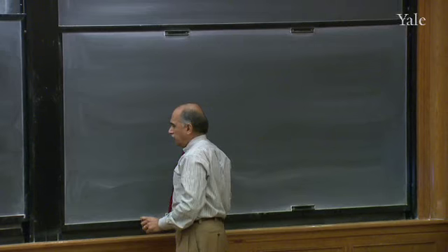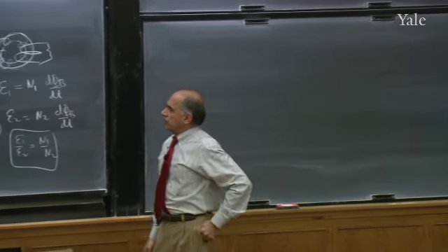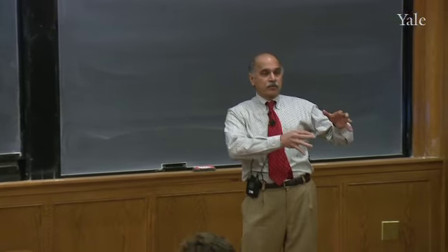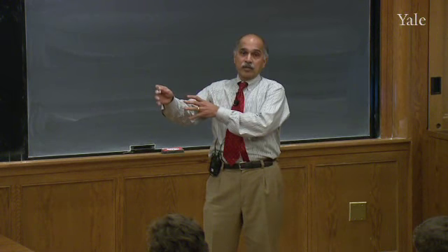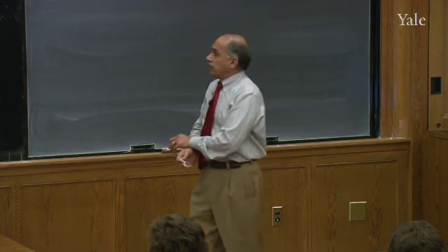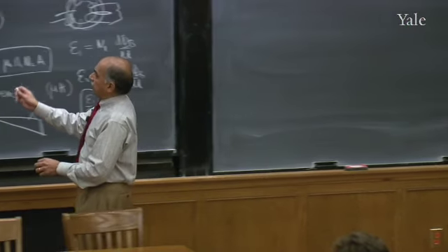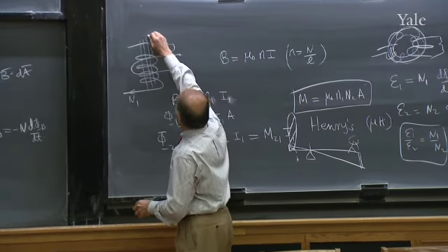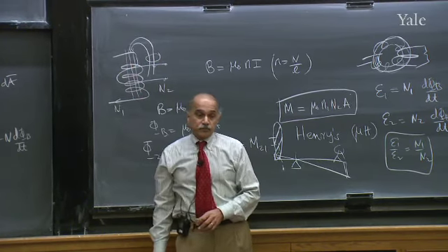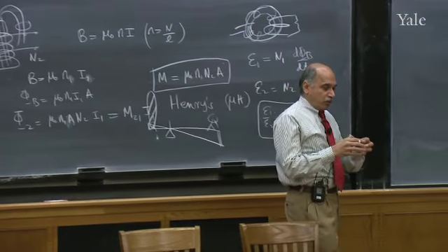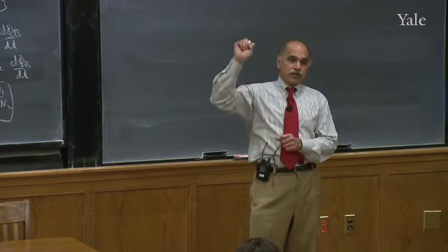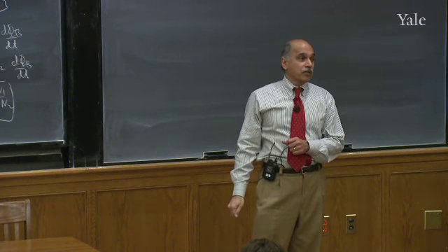Okay, now we are going to come to this part, which is really a curiosity. I'm not going to use it very much, the notion of mutual inductance. Mutual inductance is one coil trying to generate a voltage in a second coil because they share a flux. And when it's changing in one of them, it's also changing in the other one. Now, they don't have to be really coaxial. You can put a second loop way over here, and maybe some other extra flux coming out is penetrating this. There's a mutual inductance between this guy and that guy also. Anytime the flux of one coil can go through another one, you have a mutual inductance. Because if you change the current in the first coil, you're going to generate a voltage in the second coil. That's why you need to know that proportionality.